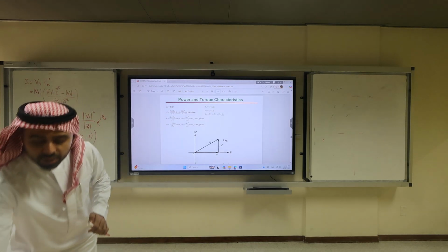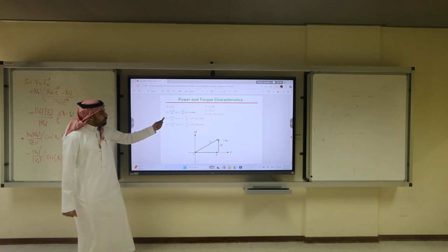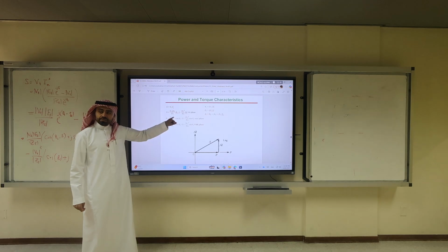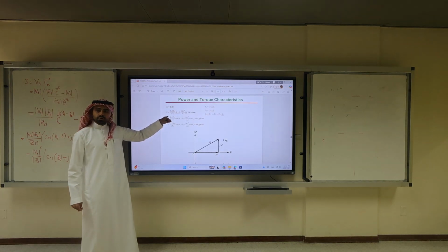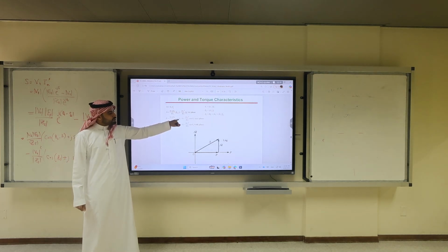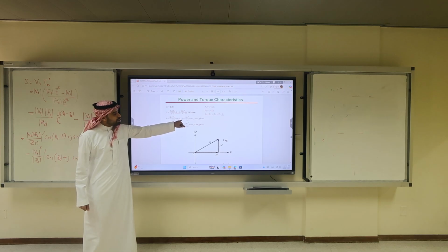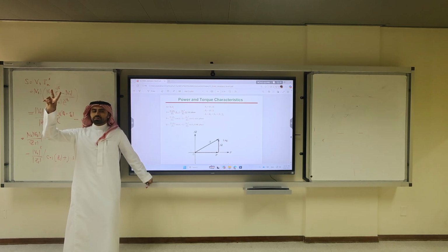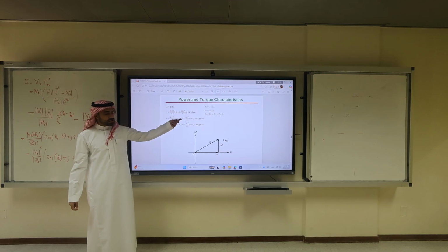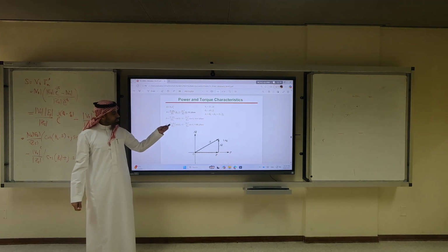Now, what do we see? We see that to control the real power, I either change the excitation voltage, E_f, Vt has to be kept at rated. Z of S, you can change it by adding extra copper, adding more windings, adding more impedance. If you change it, you will change theta of S and the torque angle. So you have two methods of control. Change the excitation voltage, which basically tells you changing E_f and delta, or change the impedance of the generator.